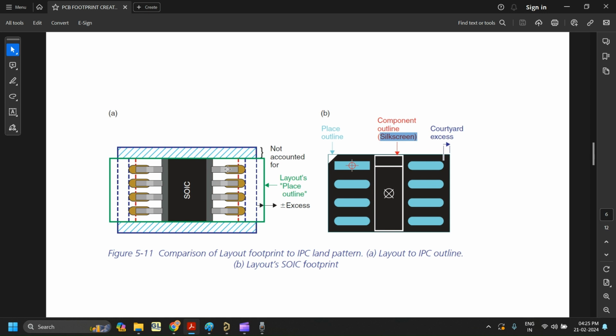Okay, for this kind of components, for ICs, my strong recommendation is you have to strictly follow the datasheet, because for ICs there will be chances of special datasheet recommendations. In that case, don't refer to the alternative part's datasheet. You have to directly approach the supplier and ask for the datasheet recommendation.